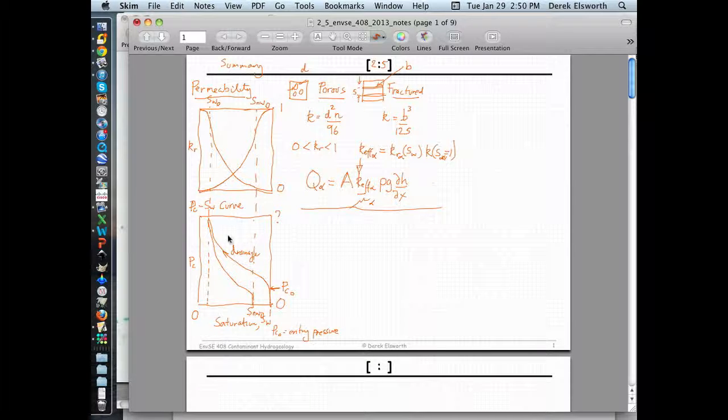The other things that we talked about in terms of relative permeability curves, also defined in terms of the same diameters of capillaries or the apertures of fractures, was that this entry pressure H sub C0 would be equal to 4 times the interfacial tension divided by the diameter and the unit weight of the fluid, the density of the fluid times gravity. If we want to write that as a capillary entry pressure, PC0, we just multiply by the density of the fluid and gravity, so it's the same expression, but without this term in here.